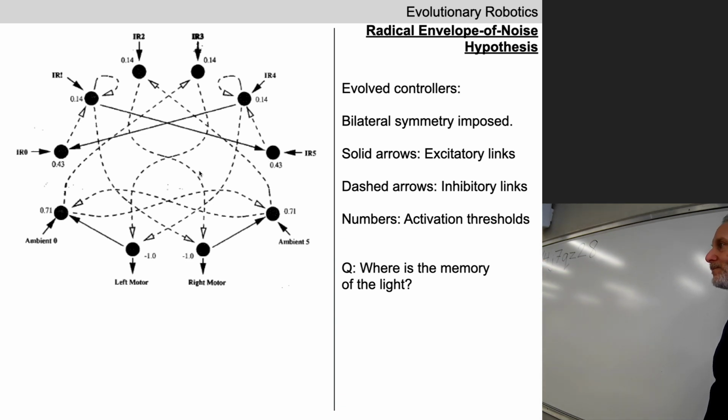If you created this first without a noisy input, and then you did like a secondary training set with a noisy input, would it just evolve to have a filter? That's a great question. That would be a perfect A/B test. Yeah. Evolve a robot in a noisy simulator. What kind of evolved behaviors do you get back? Then do the same thing, but evolve controllers in a non-noisy simulator. Then expose them to a noisy simulator and continue evolution. Which one produces more robust behavior, less robust behavior? Do you get different behaviors? I don't know the answer. That would be a great thing to try.